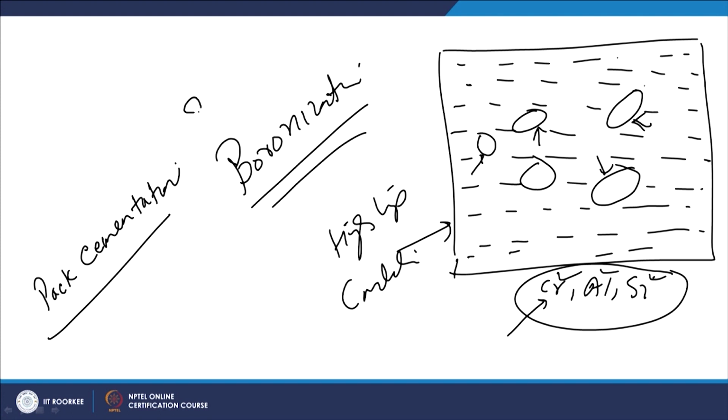Similarly, solid carburizing is also an example of pack cementation, and likewise chromizing, aluminizing and siliconizing are also used, where the material enriched with the required element in powder form is kept in a box.